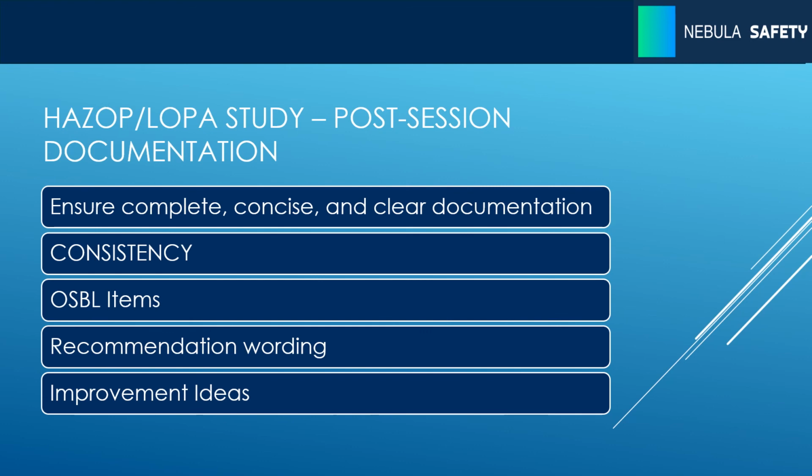So you want to make sure that you are primarily using your PHA to identify those risk drivers, and otherwise just put any sort of improvement ideas in a separate document, provide that to operations who can then do this item if they decide they really want to do it. Just keep the focus on high risk items, help prioritize these over maybe other nice to have items.